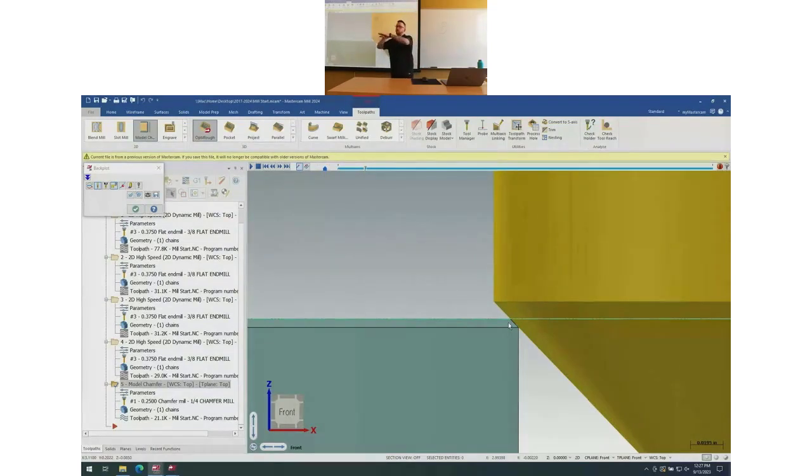When you get into a corner, where your tool's coming up on a sidewall and you're going to crash, it's going to cut that a little short. It's not going to get all the way in there. That's a limitation of the tool size and the corner. Like, you physically can't get the tool in there. You could try to drop it a little farther and come farther out, but that's not supported with the model chamfer toolpath. Where is that setting for avoidance?